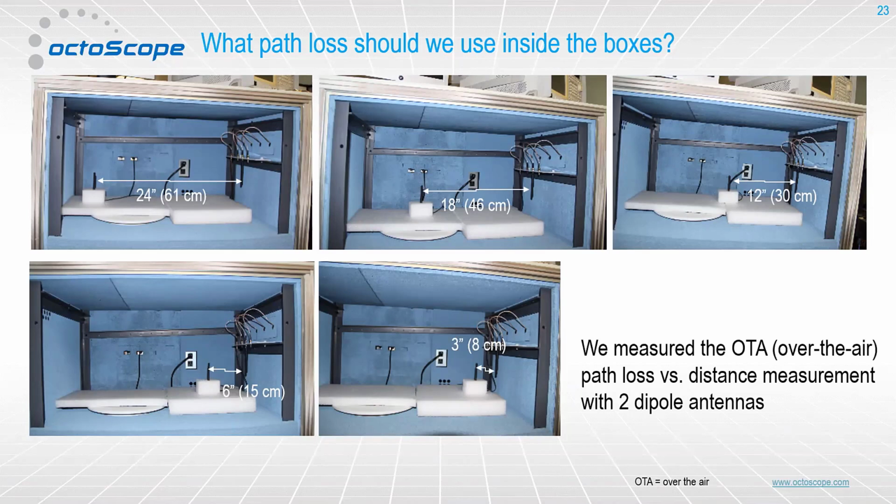I believe it does. What we're showing here is that the environment in the box is basically free space. We've damped down reflections, so we're not getting the effect of multipath from the box itself, and we don't have reflections from other elements in here, and the environment is not cluttered. So essentially, between any set of antennas, we're getting a free space model. To support MIMO, we would have, let's say, 4 antennas here and 4 antennas here, and between any pair of antennas, we're seeing free space propagation.